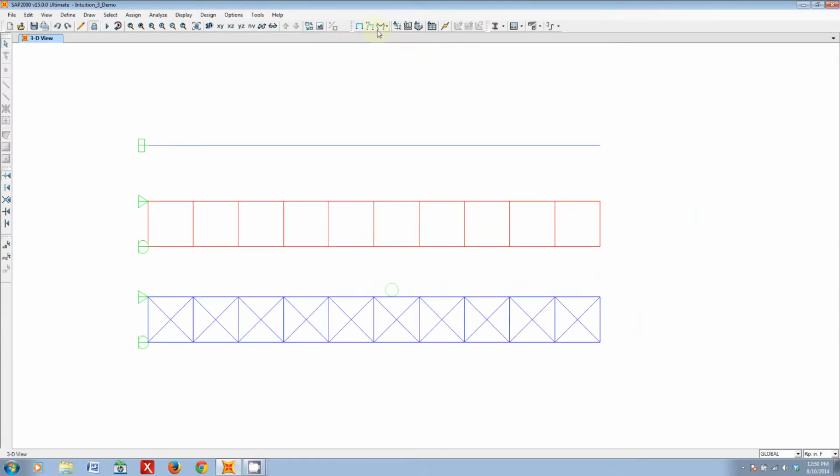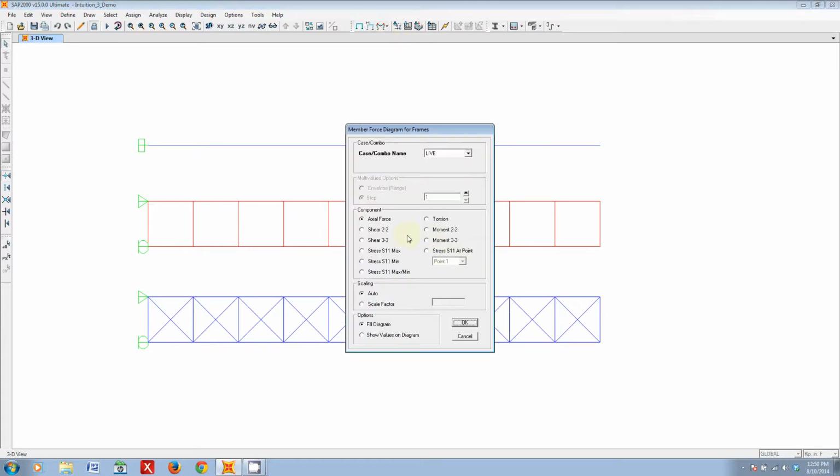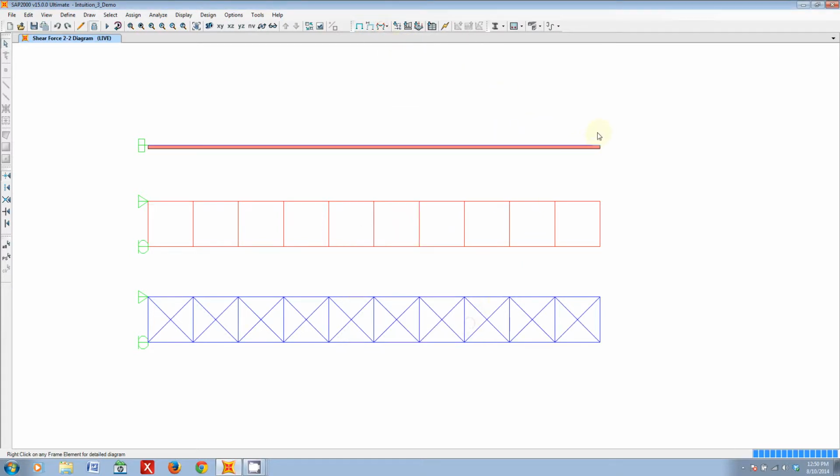So we can use that same heuristic to analyze the next model. In this example, we're just going to look at a simple cantilever beam. In this case, I basically have a point load on the end, so that means our shear force should be constant throughout the beam.